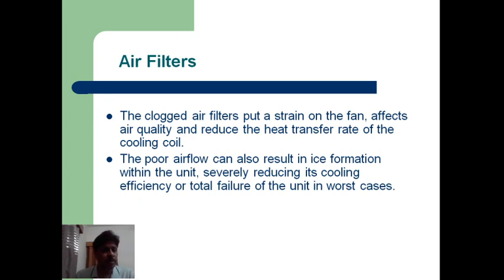So next, poor air inflow can result in ice formation within the units. If for a long duration you do not clean the air filters, the air will slowly stop flowing inside the unit, and in this way after some time there will be ice formation in the unit. There may be ice formation on the cooling coil, and your AC may ultimately fail at one point.